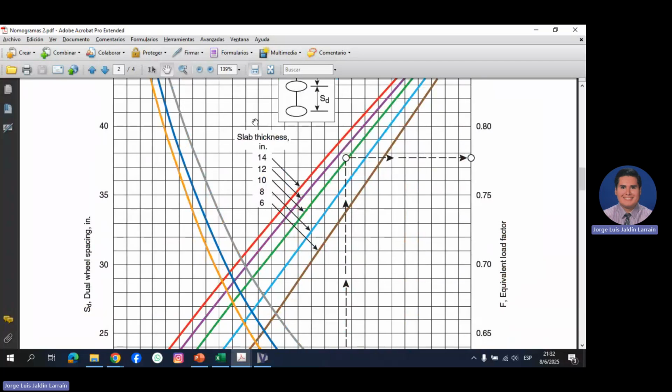And that's the beginning of some mistakes we can make in order to calculate the slab thickness, because we have to iterate many times assuming a slab thickness until we converge on only one value of slab thickness. So we have to obtain slab thickness assuming another value, and there must be a convergence. The difference between the assumed value and the last value should be very, very small.